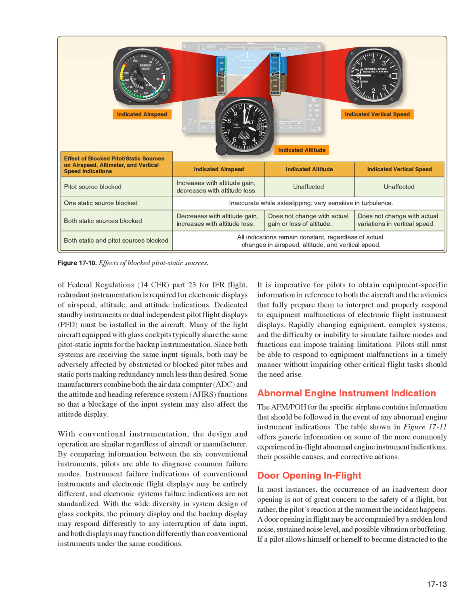Some manufacturers combine both the Air Data Computer, ADC, and the Attitude and Heading Reference System, AHRS, functions so that a blockage of the input system may also affect the attitude display. With conventional instrumentation, the design and operation are similar regardless of aircraft or manufacturer. By comparing information between the 6 conventional instruments, pilots are able to diagnose common failure modes.